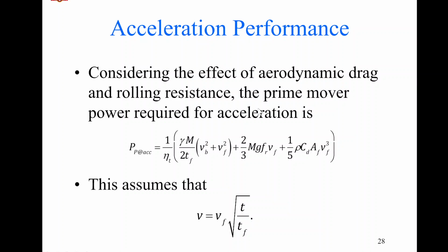So if we are considering the effect of aerodynamic drag and rolling resistance, the prime mover power required for acceleration is given using this expression, where we are adding the rolling resistance term as well as the term from aerodynamic drag.